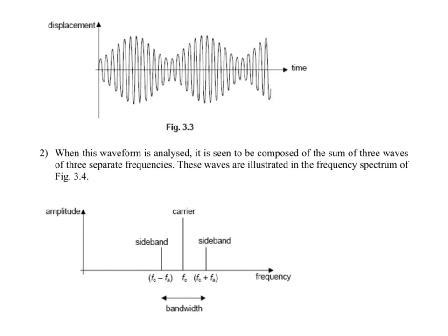So similarly, when you pass this amplitude modulated wave through a frequency analyzer, it will tell you what the hidden waves are, that means what their frequencies and amplitudes are that make up this wave. But of course, we don't purposely create the three hidden waves. We only do amplitude modulation. That means we just move up and down with big amplitude and small amplitude. That's all we do. But after that, it consists of three hidden waves.